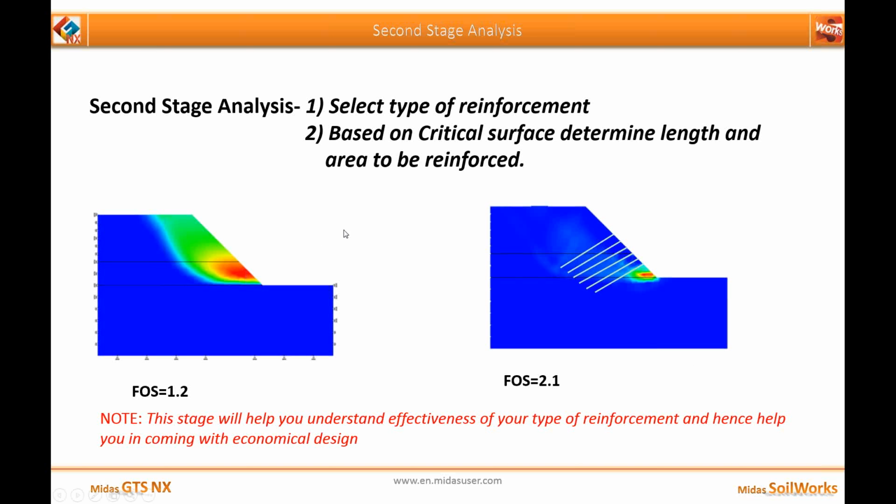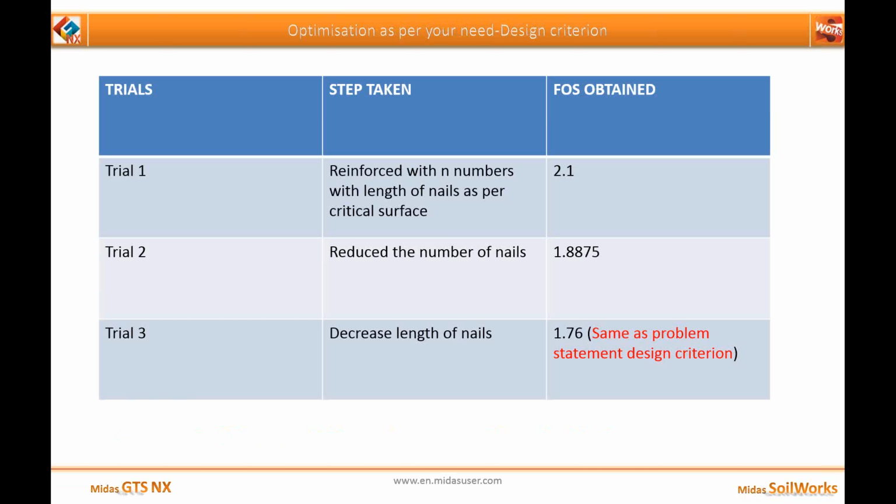Moving on to the presentation part. Now you need not do anything, but what you will be doing is the optimization as per your need, which will be based on your design criteria. For example, for the same model, I started with trial 1, where I reinforced with n number of piles with the length of nails as per the critical surface. I obtained a factor of safety of 2.1.